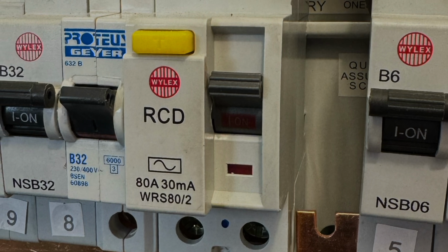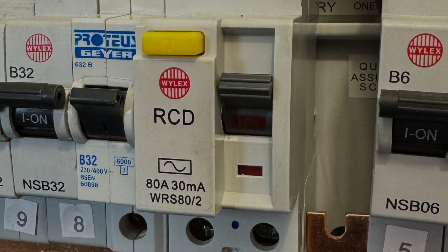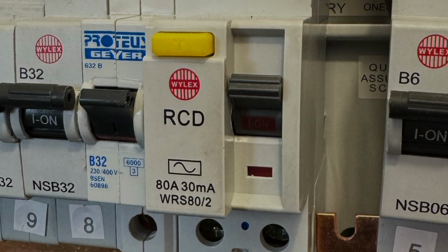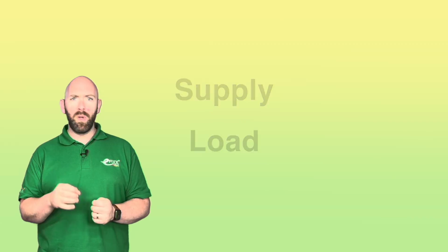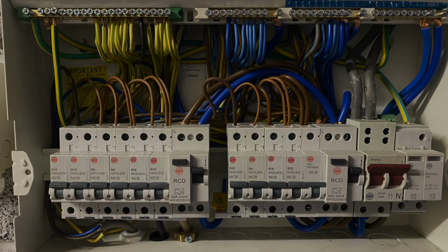One of the issues with installing a circuit on the load side of an RCCB is the device itself. Many RCCBs, RCDs and RCBOs need to be able to distinguish the difference between the load and the supply. For example, if we look at this split load consumer unit here with an MCB feeding the inverter, the current flows from the supply through the RCCB supply termination and to the inverter.